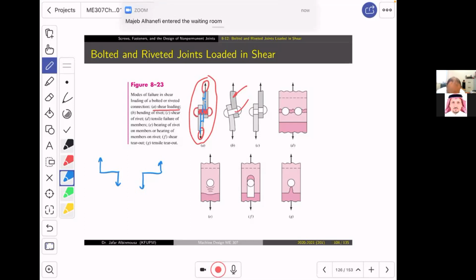So what happened? This bending that you see, bending always produces this curvature, right? So this bending that you see is because the members themselves started to lose their strength. They started to deform due to that moment.